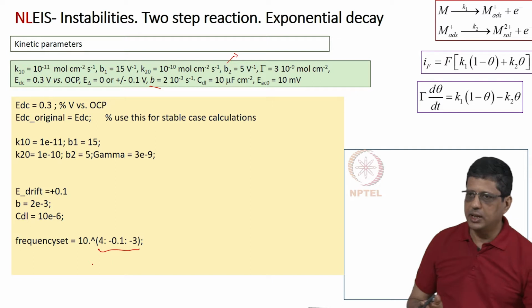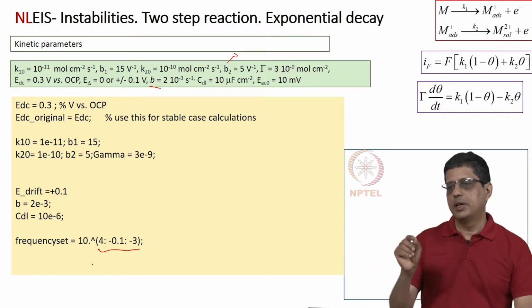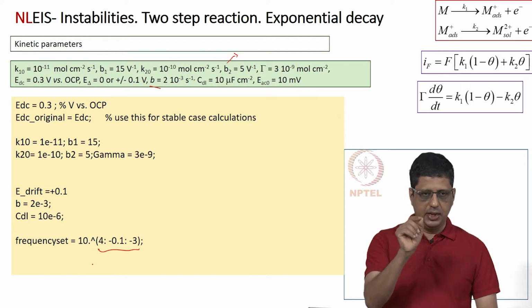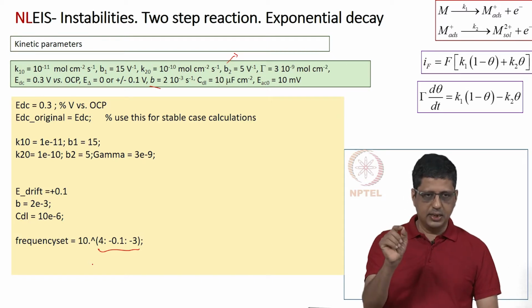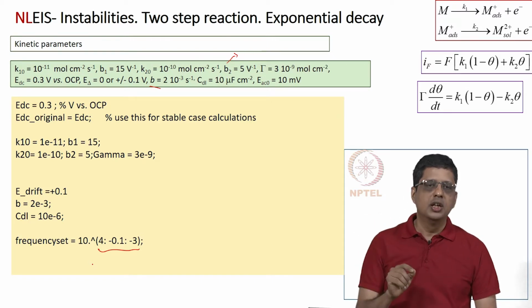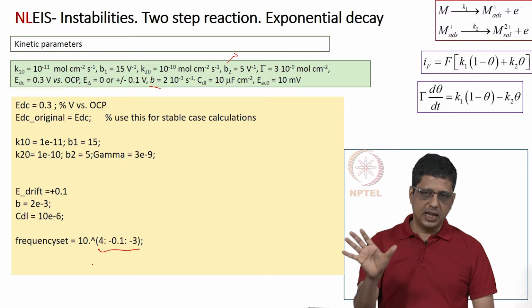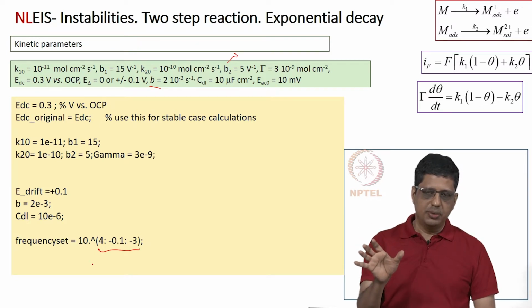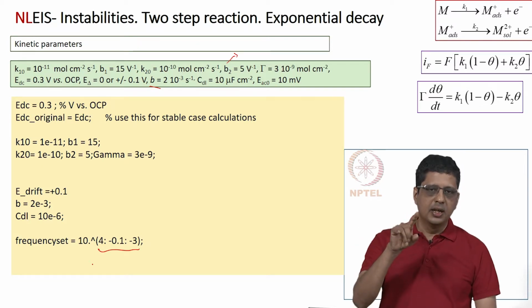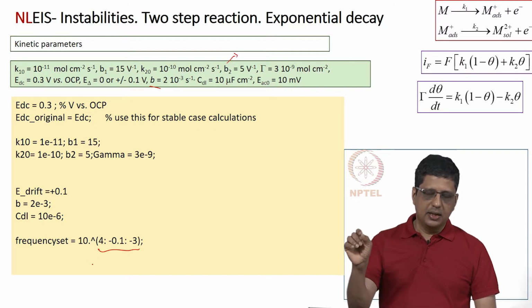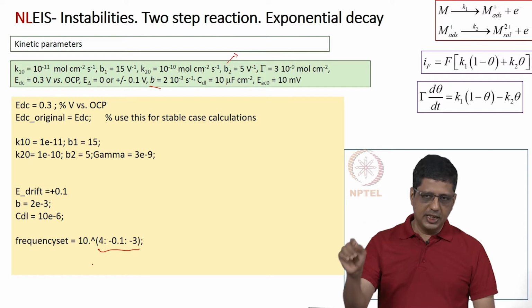Now, you can understand, if I give 10 frequencies per decade, it is going to make measurements from 10 kilohertz, it will take certain time to come to 1 kilohertz, then 100 hertz and so on. If I use 5 frequencies per decade, I will come to the 1 kilohertz fast. That means my measurement time is less, which also means I am not taking so much time to complete this, but at the end there is the DC potential at the end of this experiment.